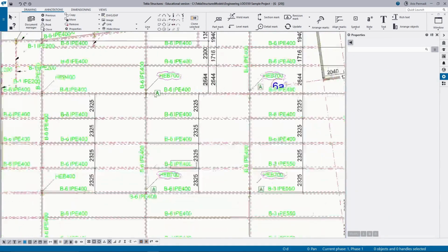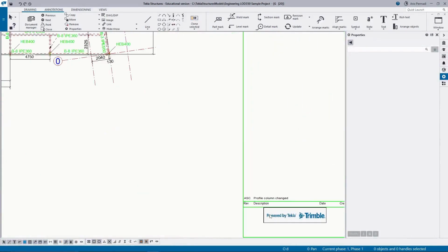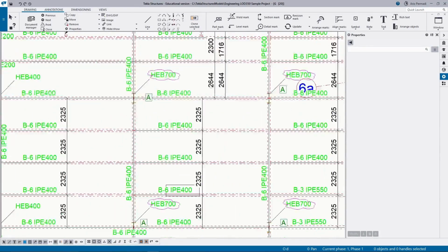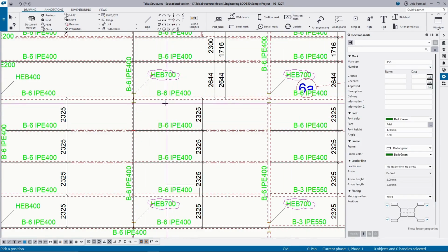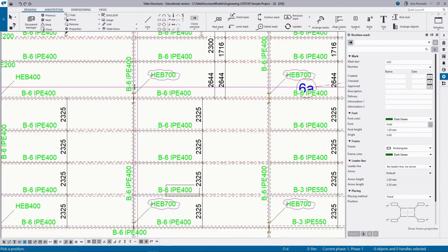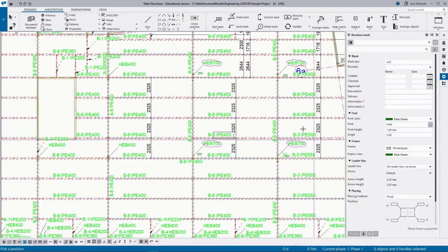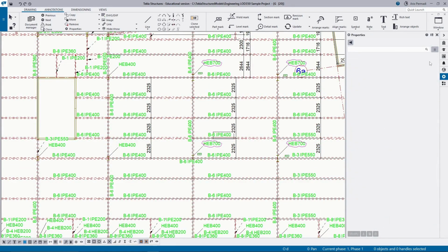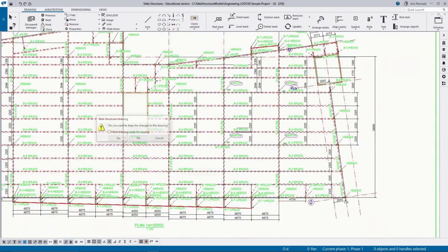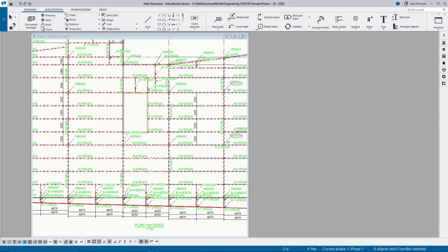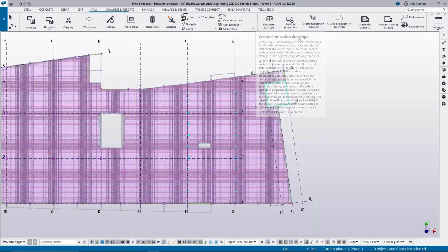Or if you have this kind of error, you can build another one again. For example, you do it again like this, with 1 millimeter of font height, so the text is not too big. Okay, you can click close. Close the GI drawing and open it again.